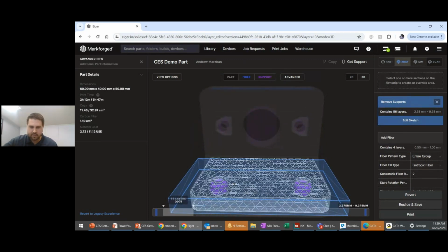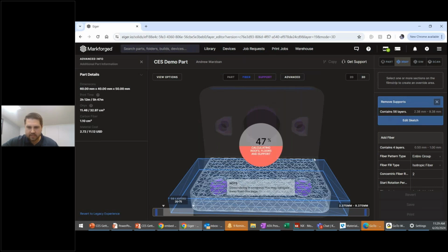Hopefully this goes without saying, but if you have a support structure in that cavity, then you're not going to have room to put the nut in, and trying to remove that support structure mid-print is not ideal. So if you do forget to turn off supports, you probably can remove that support material, but it does make life a little bit harder. So that's the first thing.